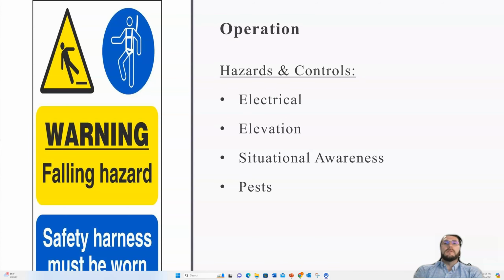Hazards and control measures to be aware of during the operational tasks should be understood, such as standard required PPE to protect from cutting and abrasion hazards. In addition, the shock hazards should be evaluated also during the voltage testing steps. So obviously you want to wear your shock protective equipment such as rubber insulated gloves with the protectors still.